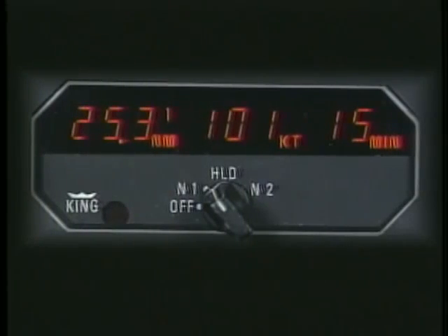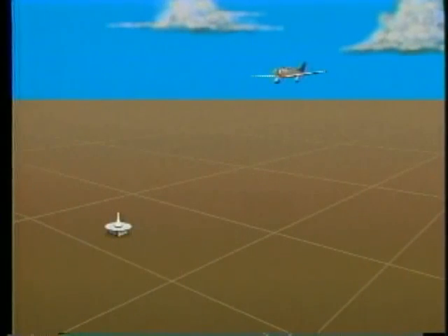Another method for identifying an intersection, as well as keeping track of your position, is through the use of distance measuring equipment, or DME. The equipment on board your airplane transmits a radio signal to the selected ground facility. This triggers a response back to the aircraft, where the time lapse is translated into your distance and time from the station, as well as your ground speed.